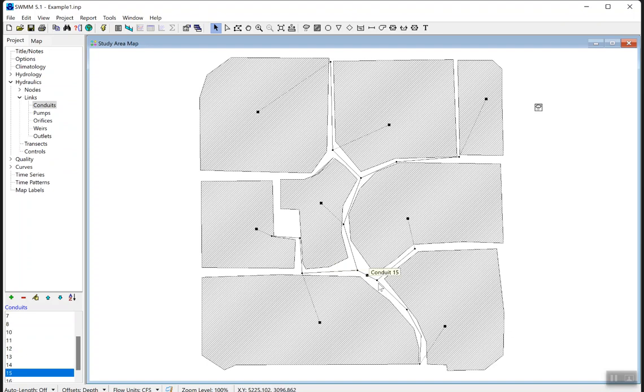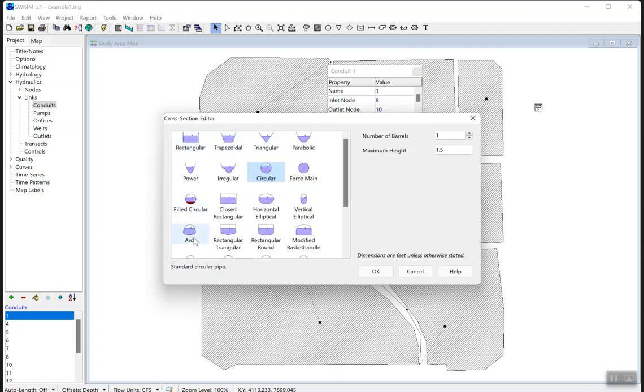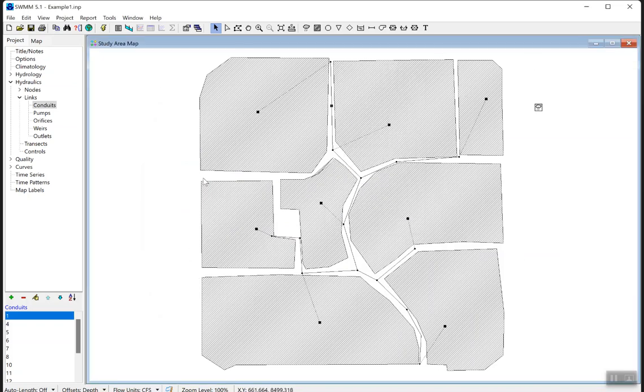And this is the main part in any SWMM model. We can describe the conduits as open channels that are connected to each other. They can be in any shape. They can be circular, rectangular, or trapezoidal, and you can select the shape of the conduit based on the actual case. Great. So as I said, this is the shape of any complete SWMM model.